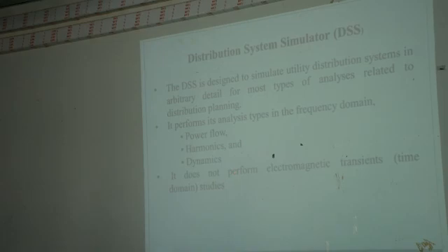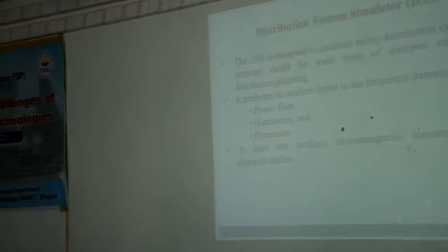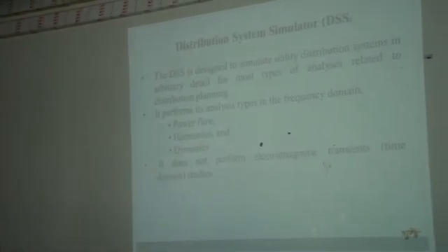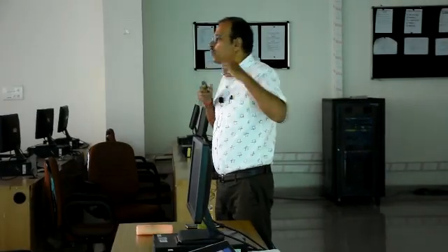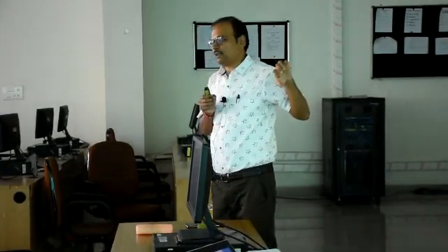EMT analysis is not possible till today, but people are working to enhance this software for EMT analysis. Now, what are the options possible? We talk about 3 control schemes for energy storage system, but by default some control schemes are also available with OpenDSS. What are these control schemes? You can have the discharge in default mode, or energy storage discharge in follow-up mode, or a price mode, or an external mode. External mode facilitates us to develop our own control scheme and interface with it.